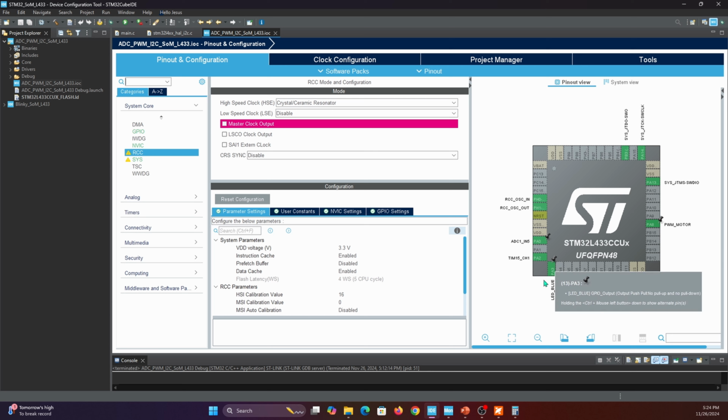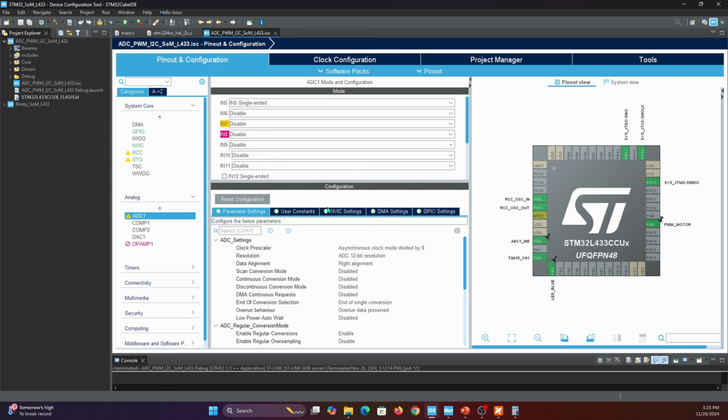So basically the working principle is we are going to read ADC values, or the voltage values coming from the potentiometer, using the ADC. And in this case, I wanted to do the conversions of the voltage values using a timer event. So every certain time, the timer will emit an event, and that event is going to trigger the conversion of the ADC.